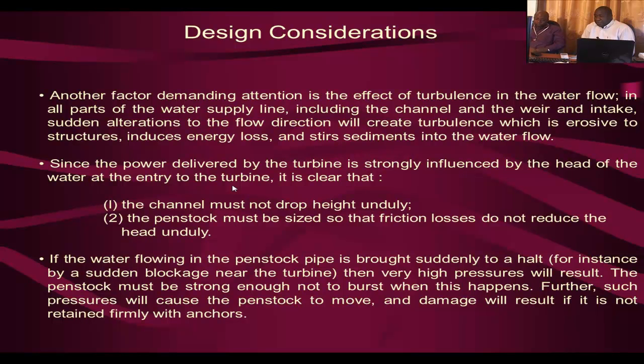If the water flowing in the penstock pipe is brought suddenly to a halt, for instance, by a sudden blockage at the turbine, then high pressures will result in the penstocks. Therefore the penstocks should be designed in such a way that these pressures will not cause any damage, by ensuring firm designs of anchorings.